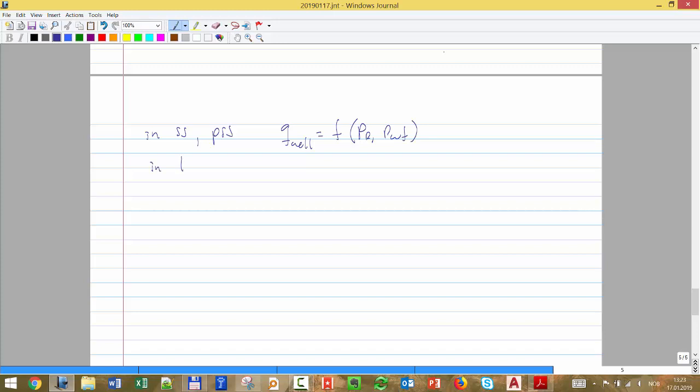However, in the transient, the Q of the well has to be a function of initial pressure, P_wf, but also of time. That complicates the treatment and the estimation of the rate quite a lot. So just to warn you, the equation we were using is in the pseudo-steady state regime, and that's why we were able to take time out of the picture. The variable that introduces time is reservoir pressure. When that goes down, that means I'm having production.